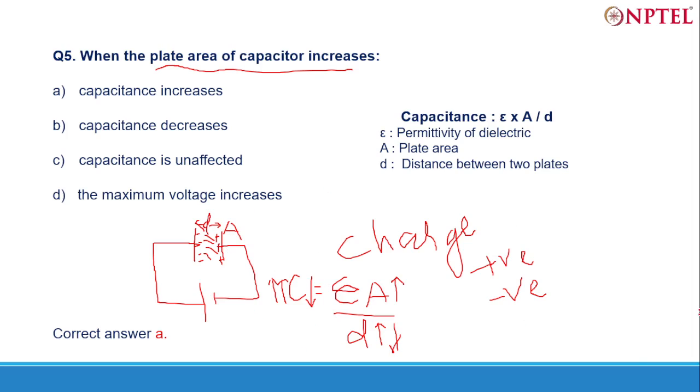Fan motor requires a very high torque at the initial level to rotate the blades, and that very high torque requires some very high charge. So this capacitor stores that charge and supplies it at the instant. It breaks the inertia of motion, and then the fan starts moving. That's one of the significant functions of a capacitor. There are many.